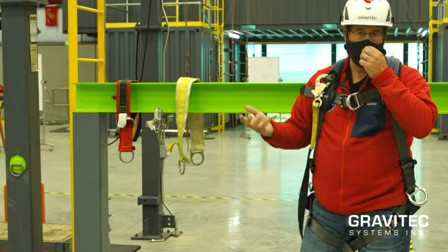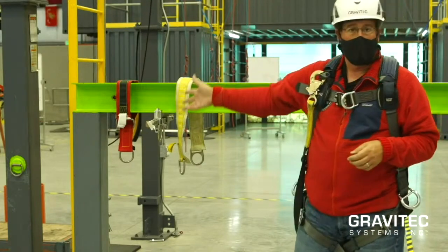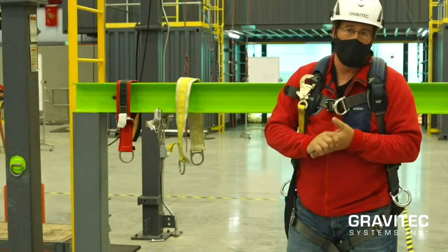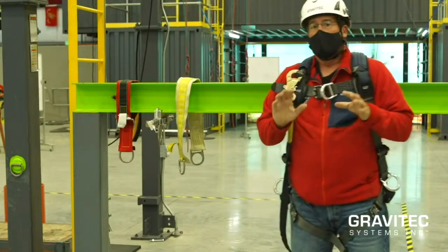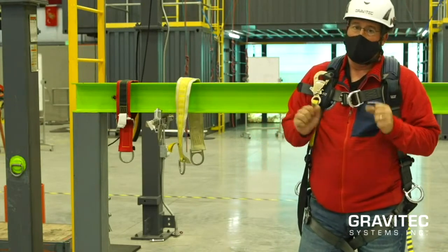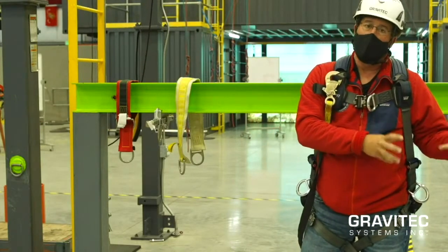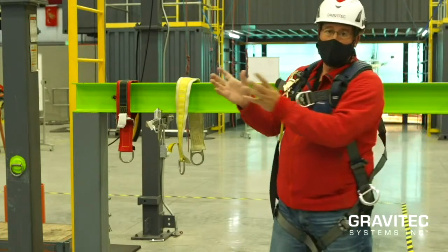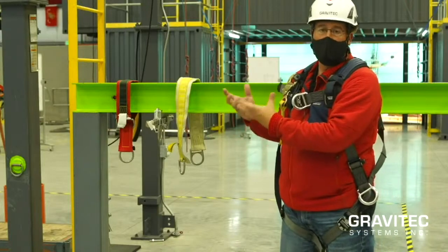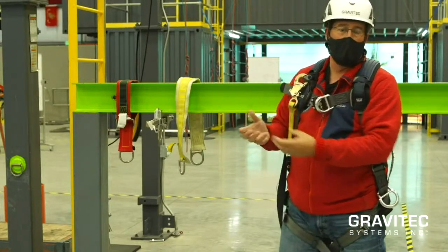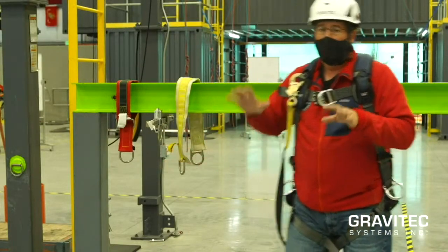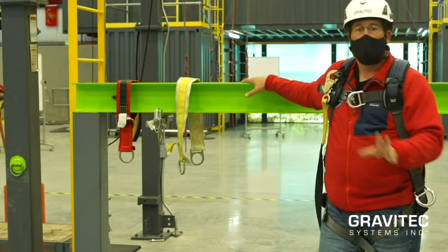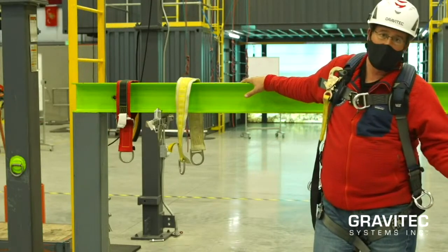And then secondly, is through testing. I grab a come-along and a load cell, and I pull it to whatever quantifying number that I need to have. So any anchor that has been proven through engineering or testing is commonly referred to as an engineered anchor. Everything else that doesn't have legitimate evidence of its strength is a non-engineered anchor. And that's the crux of the problem for employers: do I have to have engineered anchors? Do I not have to have engineered anchors? I can't have engineered anchors.